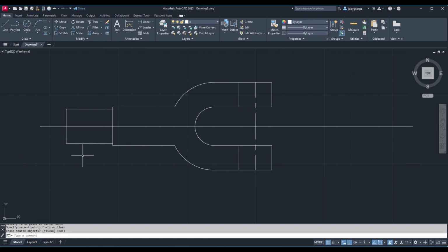So the backside, if you see, has a curved portion that is drawn by using the spline command. Make sure your ortho is off. Then I'll click on the end point and then the middle, then the other end point, then the middle, then the other end point, then the middle of that point, then the end point, then right clicking and then pressing enter to complete the spline. Now I don't want this line, so I'm deleting it.